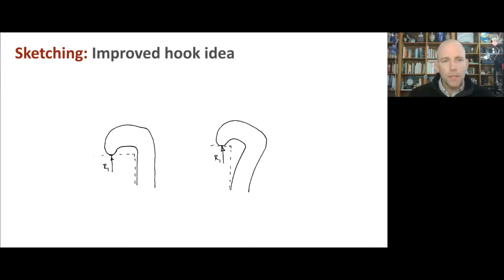And this is always a good idea, as you start to really get your feet under you in one of these design problems, to make sure that you've engaged all the different tools available to you to some degree. Some sketching, some back of the envelope analysis, but not too crazy deep, not pages of algebra, but qualitative stuff like what we've just talked about. Some sketch FEA, where you pop it into the finite element analysis and see, does the deformed shape look like what you expected? And printing something, testing it, and seeing if it behaved qualitatively, approximately the way you had expected. And if not, that can be a great sign, something you learn from, to go back to some sketching and hand analysis to figure out what's going on.